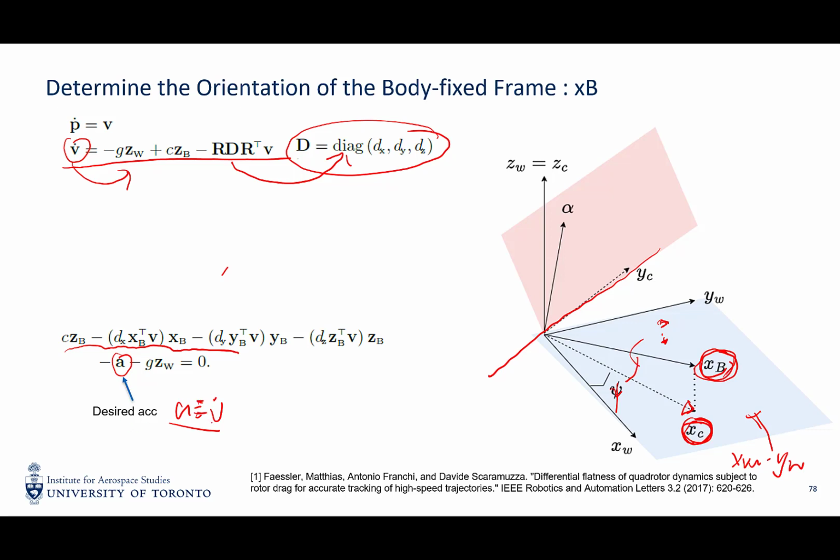It means your desired acceleration. For example, you can set your A according to the distance from your actual position to your trajectory. So here we just treat A as a 3x1 vector that can be set by a user. By moving this to the right-hand side of the equation, we have this formula. So basically, it's the same translational motion.